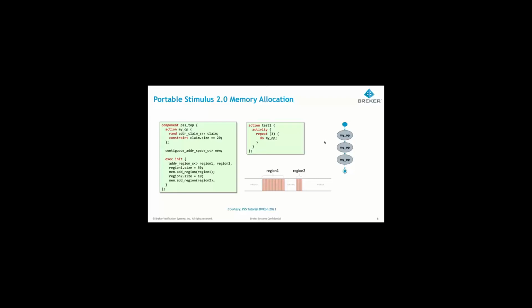So you can see here in portable stimulus, you can basically set this up. In the past, if you were writing an SoC test, you might have to actually do this manually as if you're controlling a bare metal processor. What we can do today is provide the mechanism underneath, much like a Linux OS would do, where we can schedule the memory for you and control that to stress test the whole cache system and memory system very, very fully.